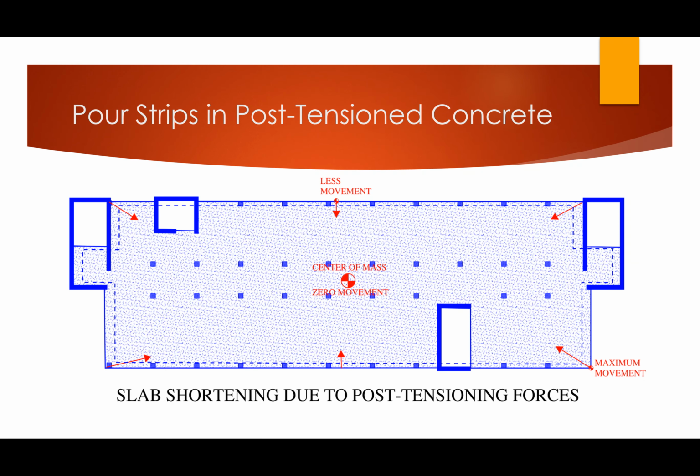And you can kind of see, let's zoom in. You can see I drew in this dashed line here what the slab is going to try to do in response, right? There's this equation in structural engineering, one of the first equations you learn, PL over AE. You apply a P, a uniform compressive or tension force into a structure or any element, and that thing either shortens or elongates according to that formula, right? So that's exactly what the floor slab is trying to do here.